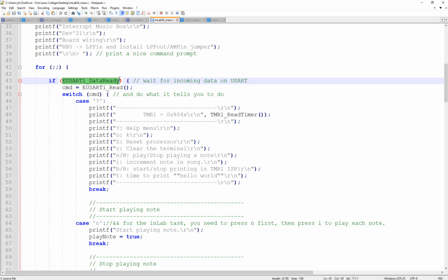But we're not doing any flags over here. It's a C level. It's upper level, not Verilog level. At the Verilog level, you have to do every single flag. Here, at the upper level, whenever this is true, just put a condition here, okay? So whenever this is true, something is received, jump into the if statement and read it. Makes sense, right? Something received, read it. You read it, it's saved into a variable, okay? And what is that? What is it? Yeah, something you pressed.